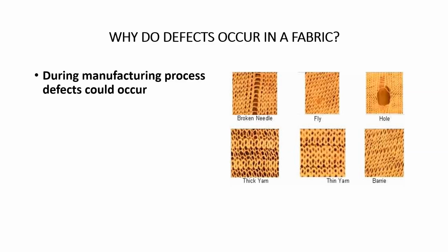So those defects are there in the fabric and have been identified during the time of inspection, and you can see how much gravity there is in those defects, easily visible. Some of the defects, like holes, are easily visible. Thin yarn, thick yarn, fly. You can now easily understand by seeing which one will be grouped as a major defect or a minor defect.